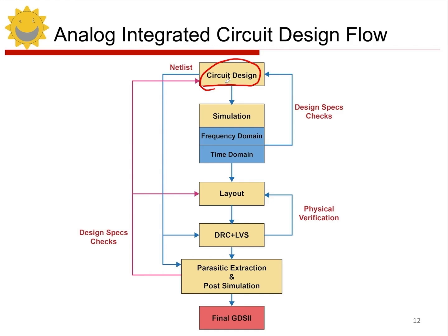Layout involves manual drawing. Consider matching and noise, as poor layout affects characteristics. After layout, perform DRC and LVS checks. DRC ensures design rules are met. LVS checks the layout. This connection forms a circuit structure, aligning its function with your design idea.